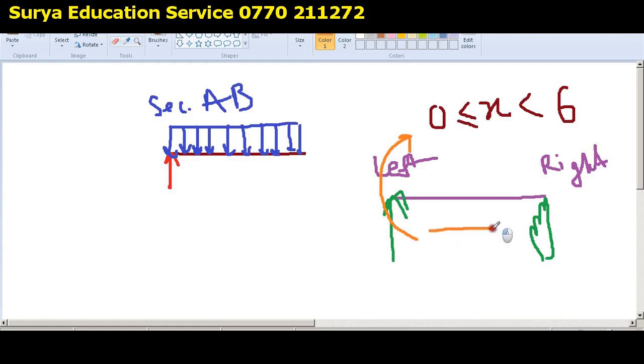This is the beam. Here you are going to apply a force, and this is the left side, and because of the force that you apply on the left side, this will go up, or in other words you can say there is a moment like this. So it is even simpler if you say the left side will go up. Very easy, right? So if the left side is going up, we call it a positive shear force. Got it or not?